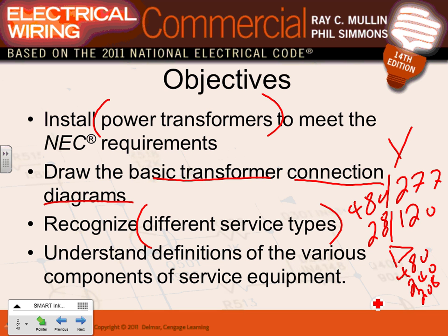So a perfect power distribution system starts with the 480, right? 480/277, step it down to 208/120, feed the receptacles, and everything other than receptacles, including the lights, will be fed from 480/277. That's the ideal one. Okay, now I can use 208 for everything, like we did for this project. So that's what you want to do.